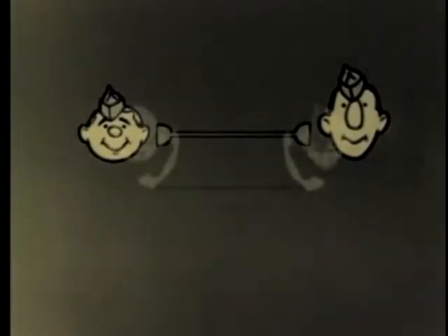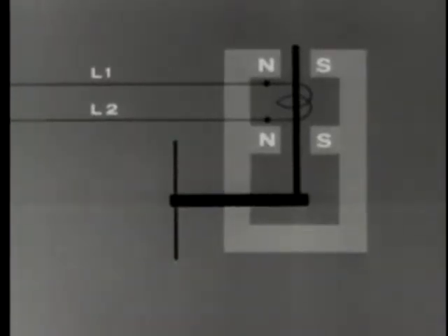Funny, funny. For convenience, a second unit is placed in parallel across the line, giving us the simplest of all telephone systems, the sound-powered system, so called because it draws its energy directly from the transmitted sound. The chief advantage of the sound-powered system is also its biggest limitation. If, for instance, our line is extended beyond a certain range, the received signal will fade out and become unintelligible. The resistance in our line becomes too great to be overcome by the weak energy of the sound-powered transmitter.